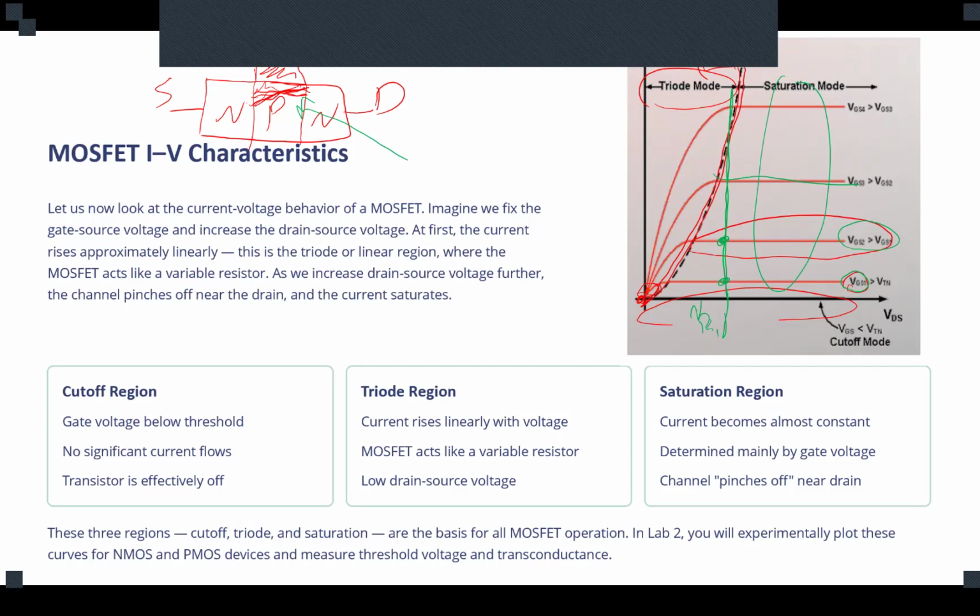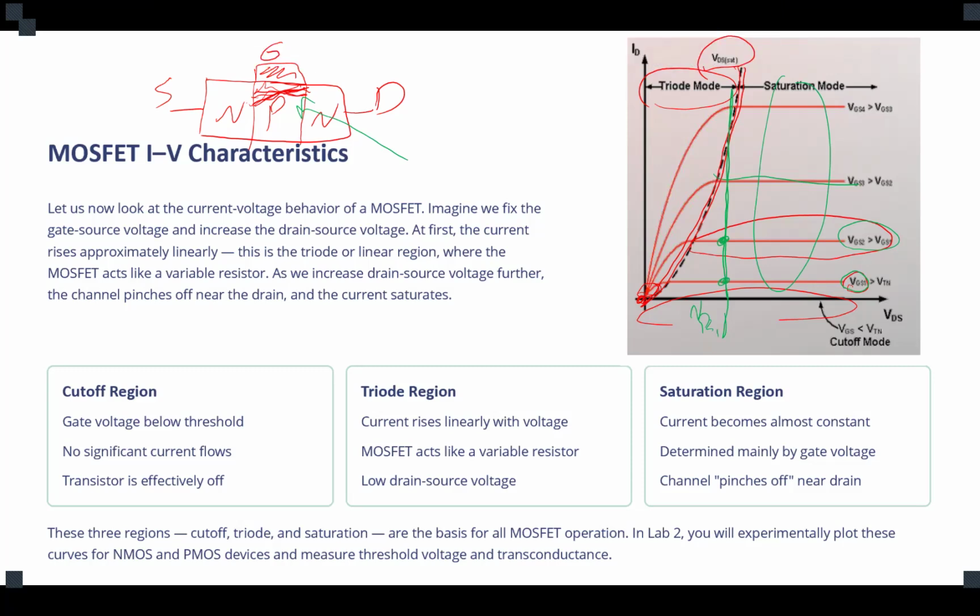Another one that your friends mentioned is that we want a more stable performance out of our MOSFET. Now, if we go to the triode mode, we don't have strong characteristics regarding the stability, because in the real world, we never have a pure voltage between drain and source.